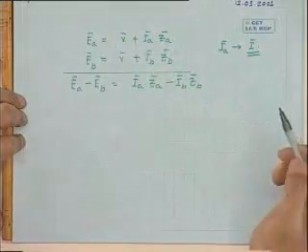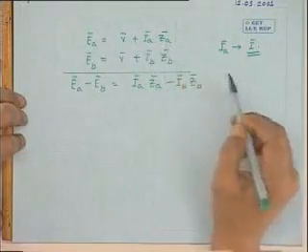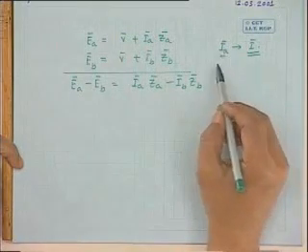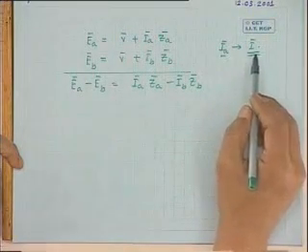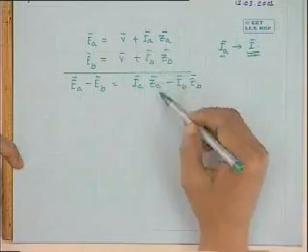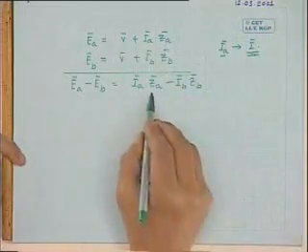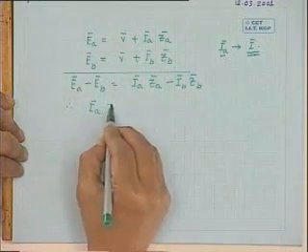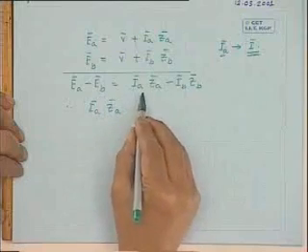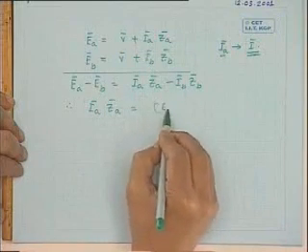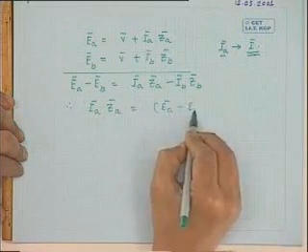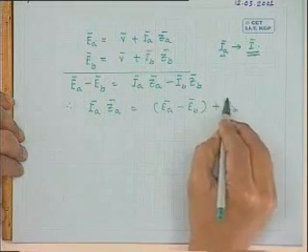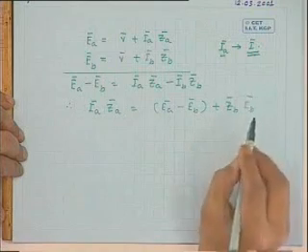This you will be getting if you subtract these two equations. In this analysis, what you are trying to do is to express I bar, IA bar or IB bar, in terms of the total load current. That can be easily done if you do it in this fashion. So therefore, what you get is IA bar ZA bar equal to EA bar minus EB bar plus ZB bar IB bar. This is correct.